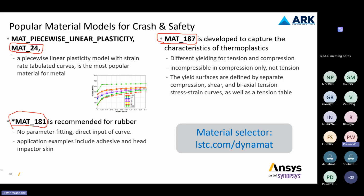But when you look at MAT_PIECEWISE_LINEAR_PLASTICITY, it is a material which models plasticity, where you can model the plasticity with strain rate tabular curves and with the help of stress strain data, that is stress and plastic strain. You just need to have the true stress strain curve data, and based on that, you need to identify the plastic region, and that plastic region you need to define in MAT 24.